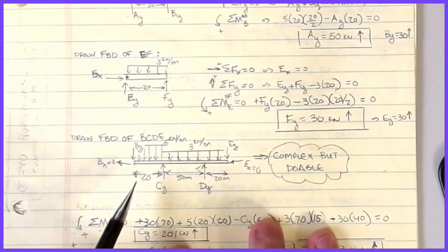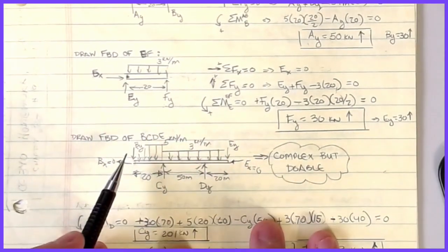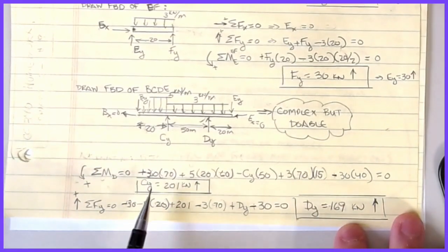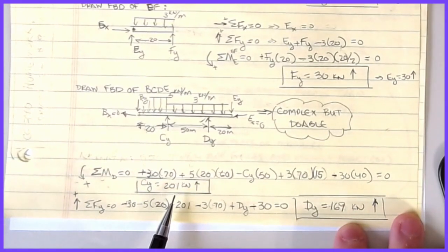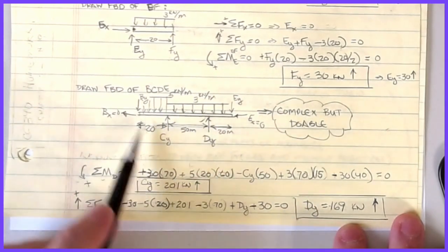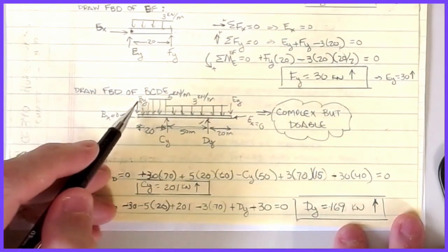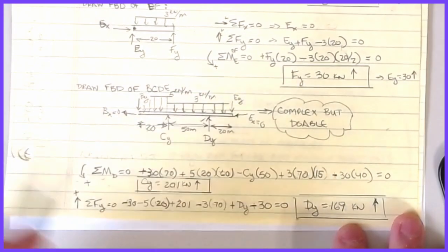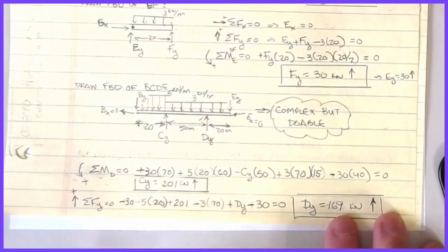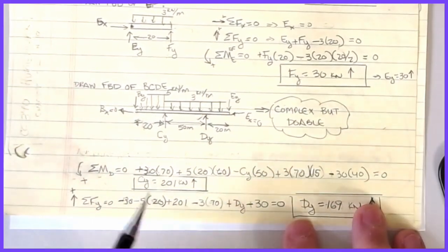All right, sorry about that. Once we have our free body diagram established, then we can go back and write our equation. And I saw a typo, I guess if you will, on here. So all I'm going to do is sum moments at D at this location on this free body diagram. Notice that I've got the hinge force By and the hinge force Ey. There's more than one way to do this, and that was part of where I kind of mixed methods and got tangled up for a second, but it's all resolved now.